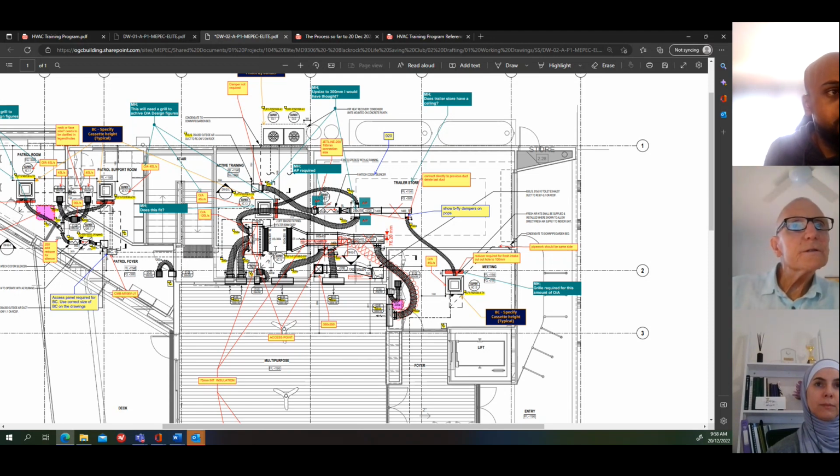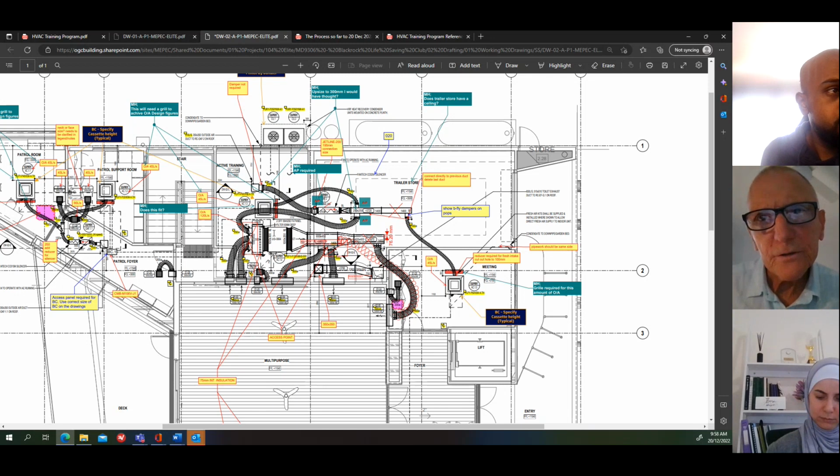Now on the air conditioning unit, it shows some pipe work coming in there. And it shows an access panel there. Don't forget that every air conditioning unit needs a condensate drain. That's very important, and it's got a drain somewhere. So you need a tundish. The tundish is normally provided by the hydraulics contractor or plumbing contractor, not by the mechanical. So it's preferable if you can get the plumber to put the tundish as close to the air conditioning unit as possible. Then we don't have to worry about the fall in the drain.